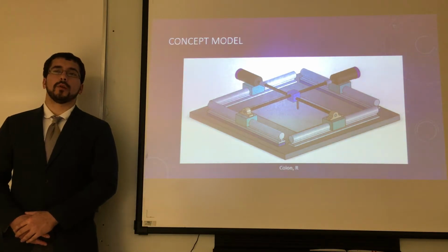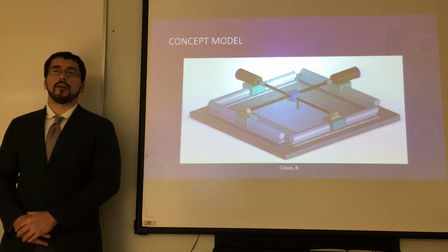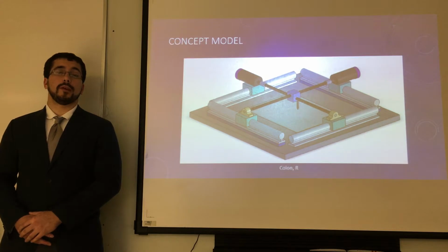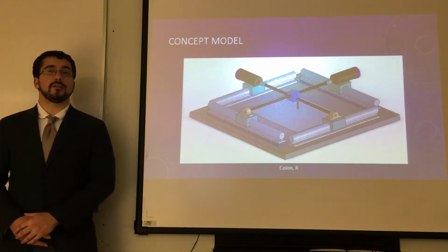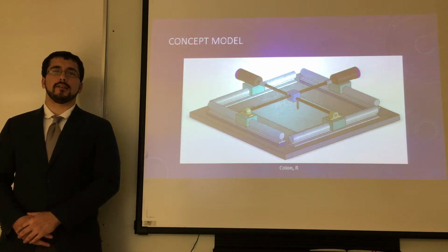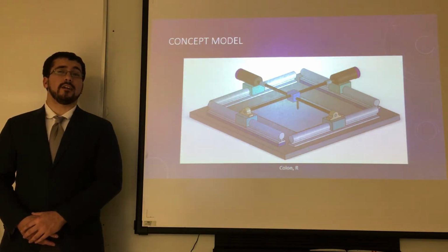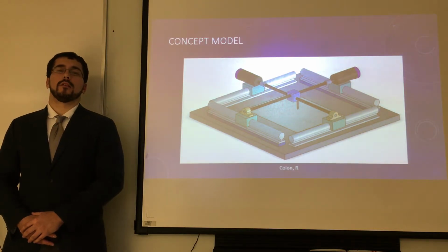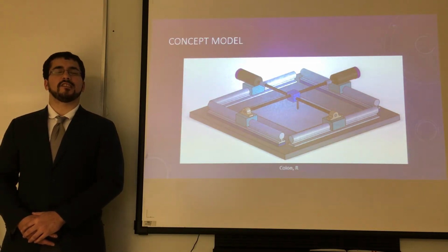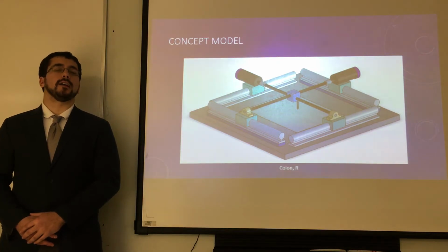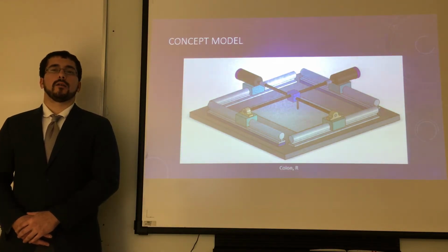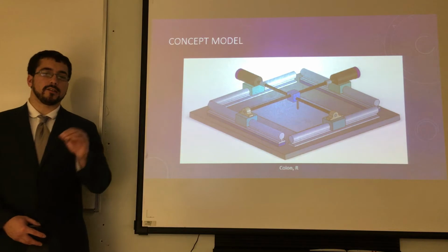Each servo motor will have an 8-bit encoder providing 1.4 degrees per bit sensitivity. These will be used in tandem with 10 threads per inch lead screws, displacing 0.1 inches linearly per revolution. Theoretically, the accuracy achievable is plus or minus 0.4 of a thousandth of an inch. Most of the error for the system is expected to come from flexibility of the writing instrument, though. There will also be that adjustment for changing the line weights.